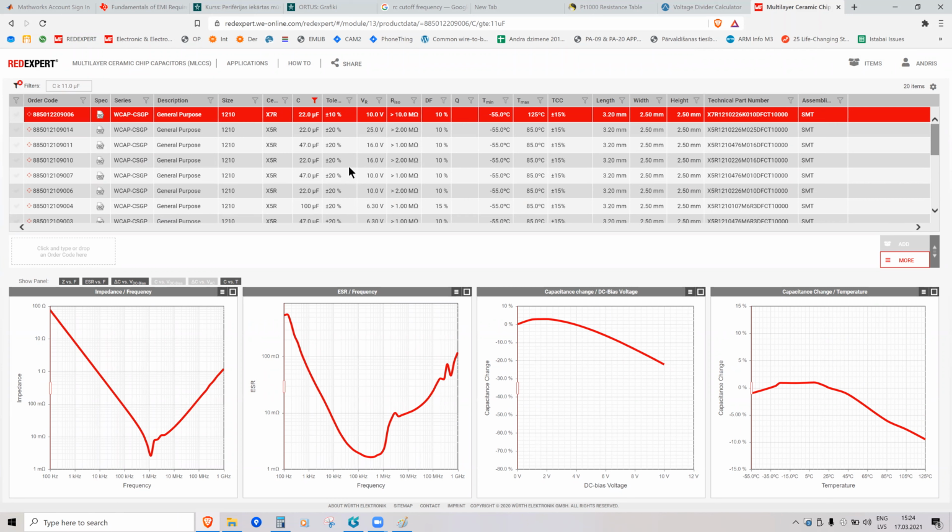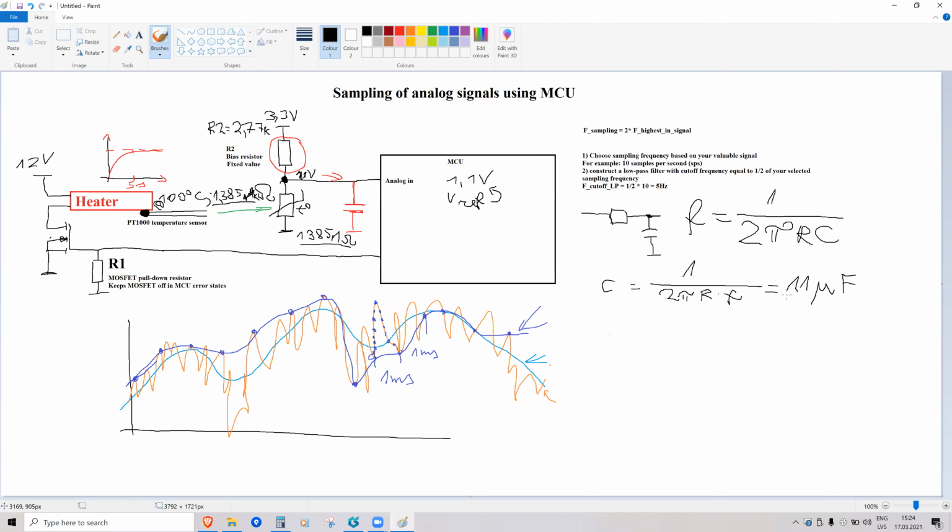which I have probably told you already. The problem with ceramic capacitors is that if their material is X5R or X7R, when you apply a voltage on the capacitor, which is what you normally do, because these plates attract, they compress the dielectric material between the plates.